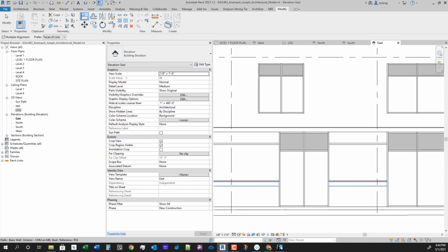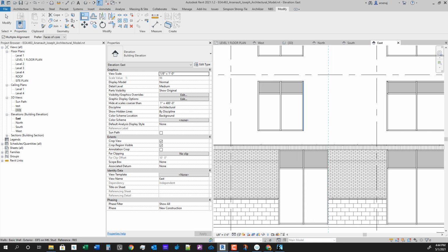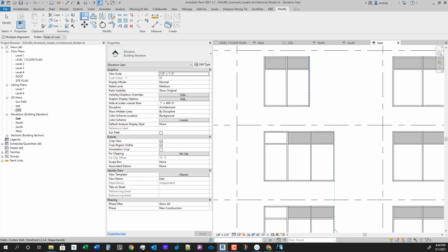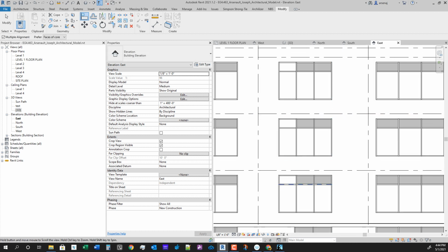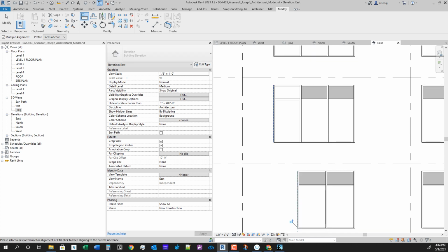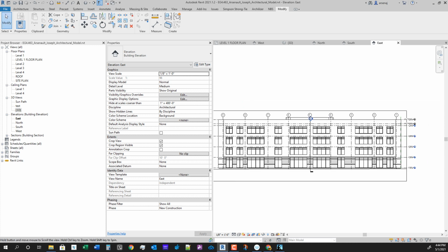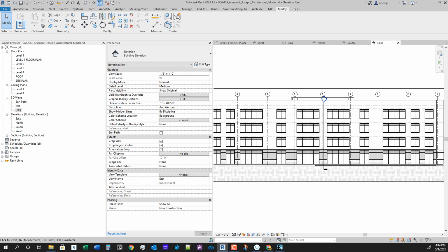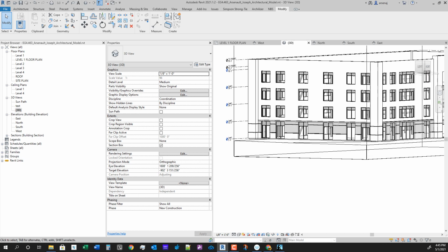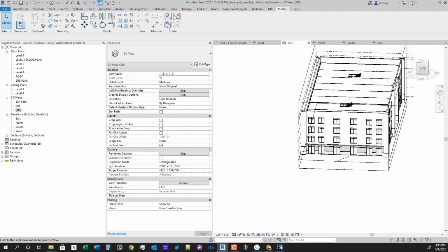And so align again. We'll align this far side so it doesn't try to make a super small window here. Hit align again to make sure that you're using a different edge to align. And then now, alrighty. That's how we fix our elevations and structure to get our windows and our brace frames to better align on our building.